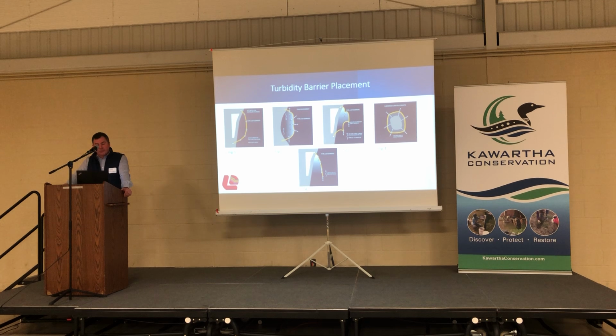The next few illustrations show very common installations and configurations of these curtains, starting with figure 1, in an application where there's very little flow rate, so the curtain itself can hold its position quite well without any assistance from anchors. Figure 2 is more representative of a tidal type effect, where you're going to have constant flow in and out of that contained zone. So we need to be really careful with the placement of anchors to hold that position in both directions.